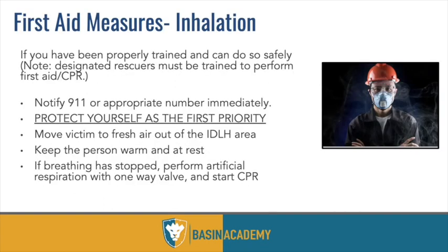So if someone does get exposed through inhalation, then we have to assess what the priorities are. And the first thing you want to do is protect yourself, right? You want to call 911. If you have two people there, the other person should call 911. If you're the only person there with the person that needs to get rescued, that needs to be your first call before you go help them.